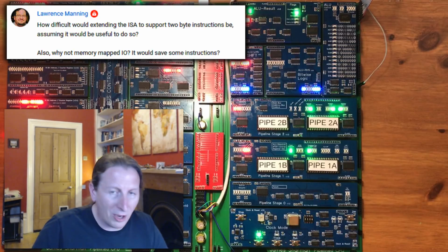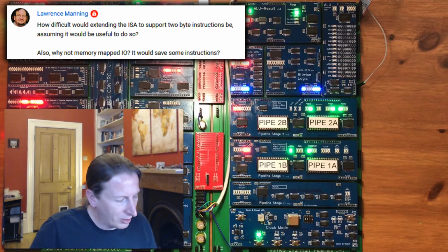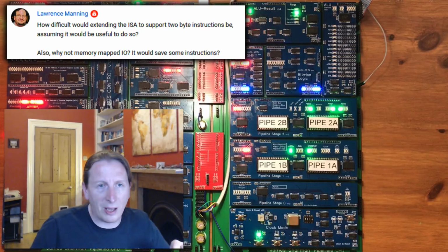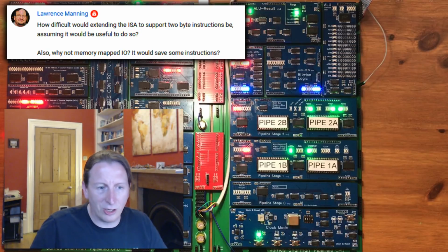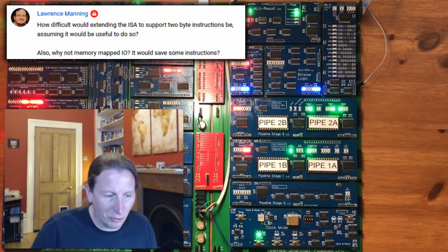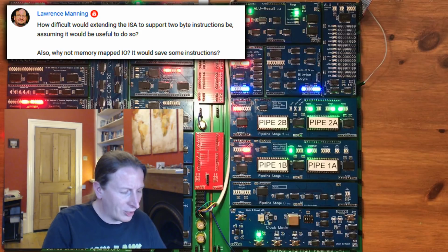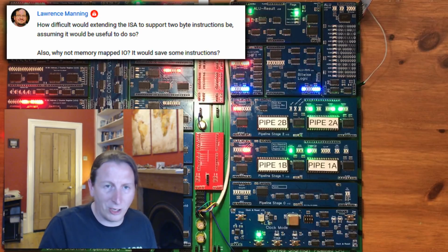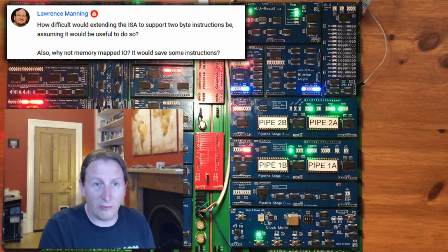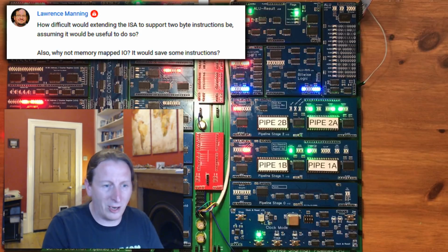I'm happy I didn't do that because I obviously rely on the fact that I've got an 8-bit data path from memory, and if I were to have a multi-byte instruction, that would be stalling the fetch unit to pull the extra byte of data in, and so it would drop my overall instruction throughput. And I'd also have this whole extra complexity in the circuitry, which would make it more difficult to explain the working. And as I've already demonstrated, this is actually a very powerful processor already without having any of that.